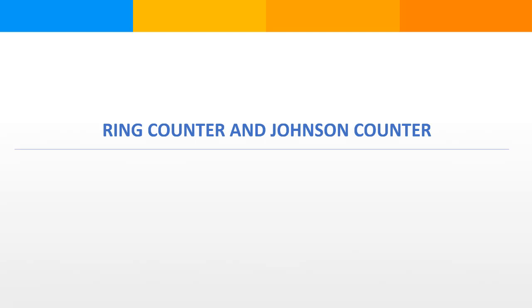Now in a synchronous counter, we are giving the same clock pulse to all the flip-flops. That means the clock pulse will be available at the clock pin of every flip-flop at the same time. So your flip-flops will be working synchronously. That is why the name is synchronous counter.